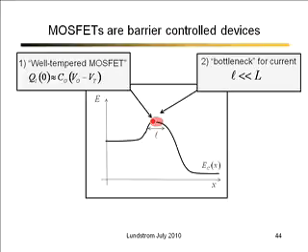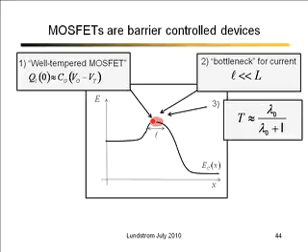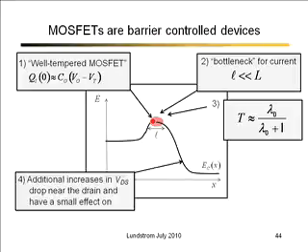If electrons can get across that region, it doesn't matter if they scatter or not. The transmission we can estimate simply in terms of the mean free path and the length of that bottleneck region. The length of that bottleneck region is a little more difficult to get. There we really need a simulation. That's controlled in detail by the shape of the potential barrier, the scattering, the self-consistent electrostatics, but we can get the gist of what's going on.